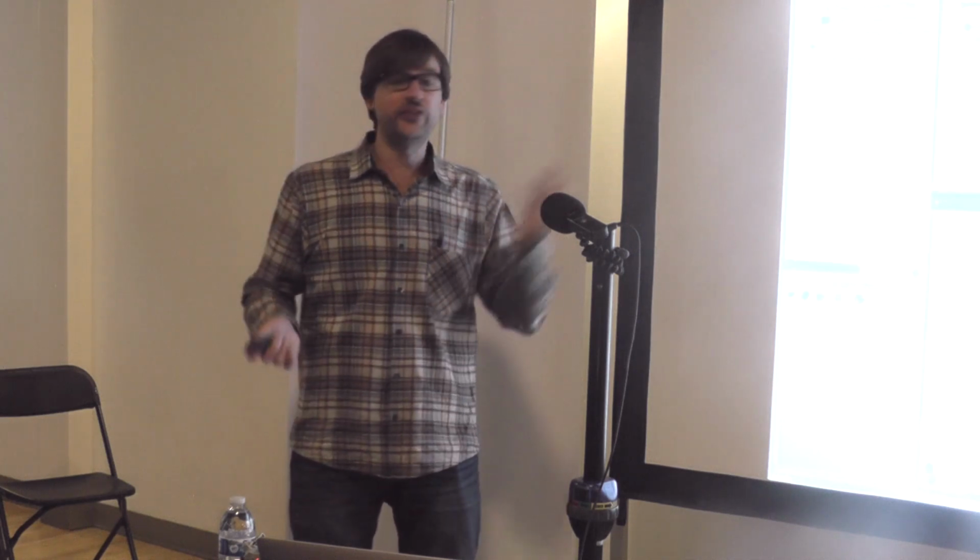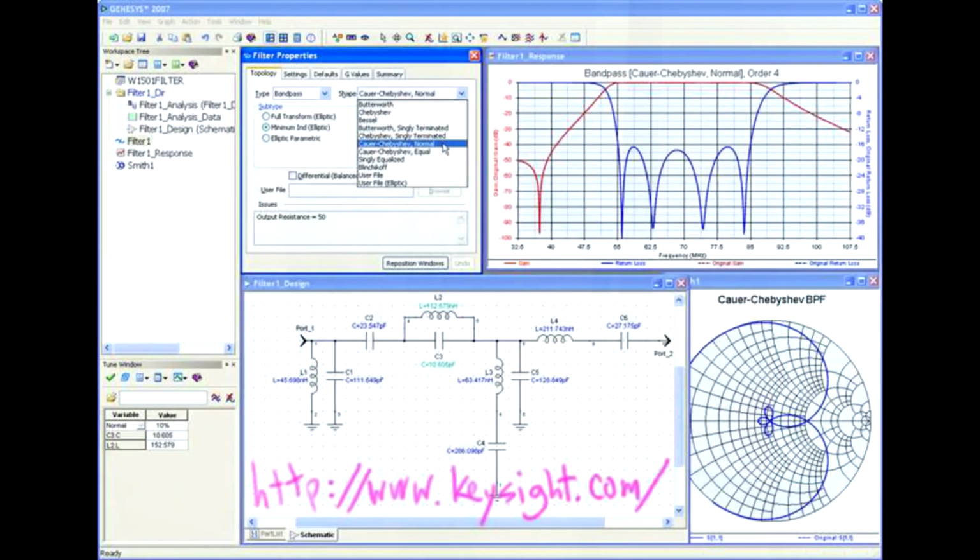Use resources that are online and available to you to find RF filters, because you can get a filter, and we'll see one later in one of my example boards, that is just a single little surface mount component that you solder on your board, and it has a known performance, known frequency response, known impedance matching. It's super easy to use, and they only cost a few cents. For almost any application, you're going to find a good filter.